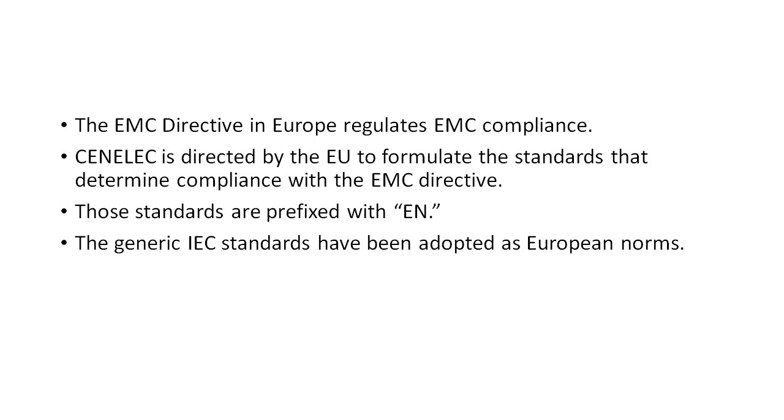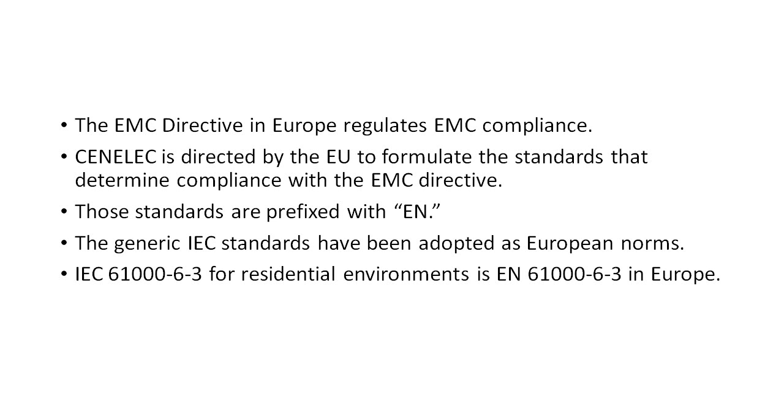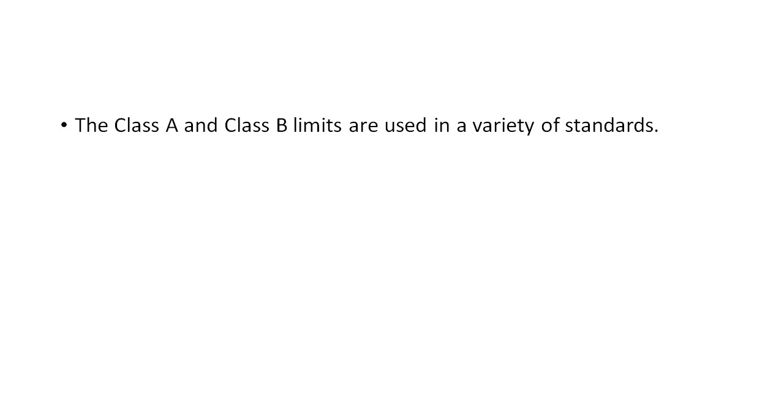Similarly, CENELEC adopted generic products test standards that are derived from the IEC's generic standards. A typical generic emissions standard is IEC 61000-6-3 for residential digital devices. The EN's version is named EN 61000-6-3. The CISPR 22 emissions limits for Class A or Class B devices are commonly used across a wide body of standards for all different products,